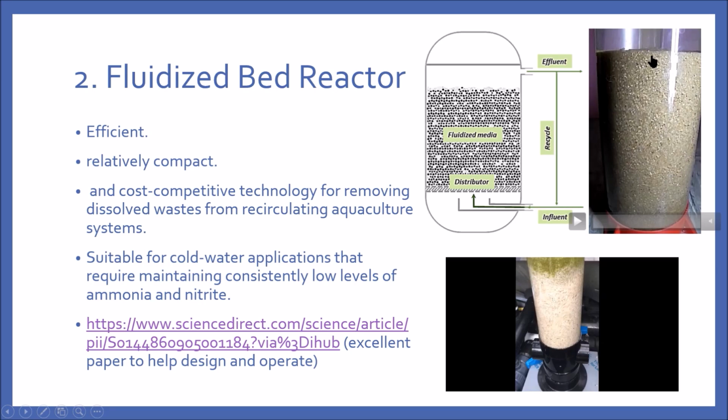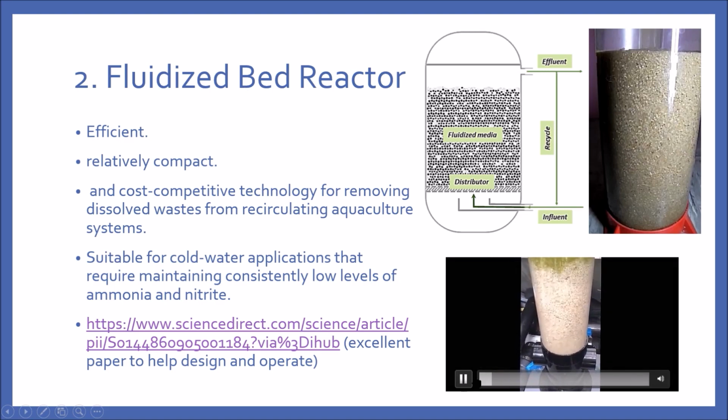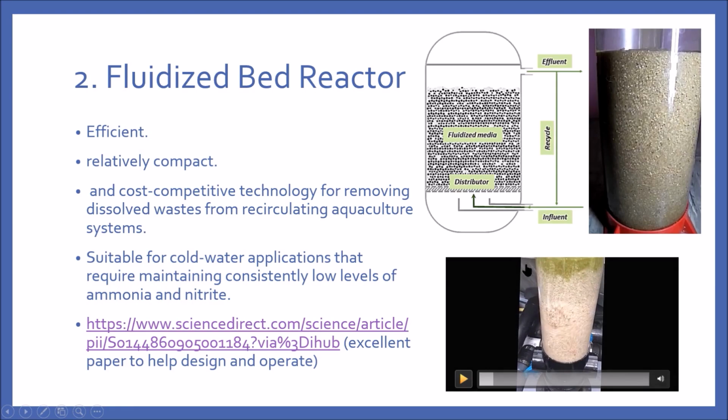So this is also another clip of how a fluidized bed reactor actually looks like. One of the reasons why a fluidized bed has gained popularity in recent years is because of a simple concept. The bacteria grow on the sand in an outward layer, so they form what we call a biofilm layer, which consists of a community of bacteria.